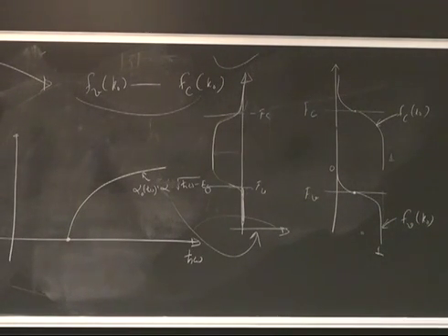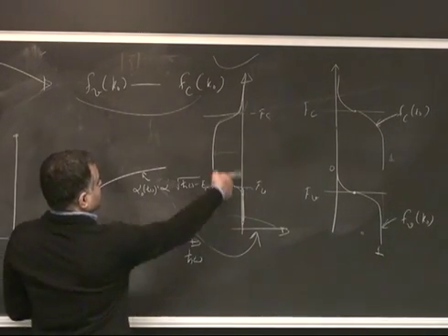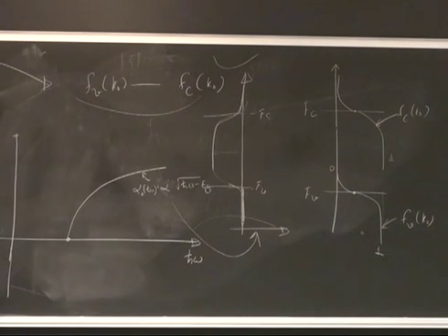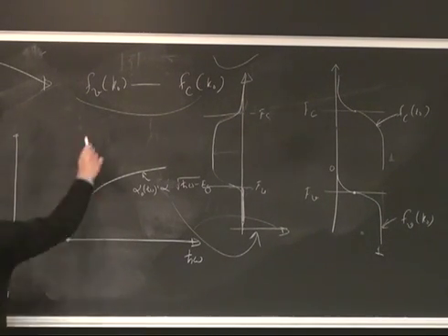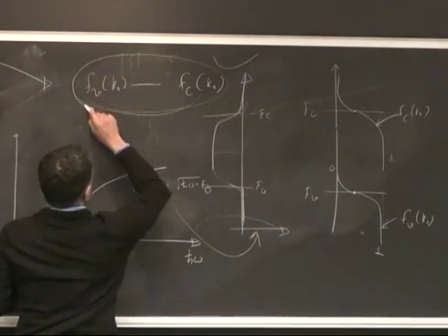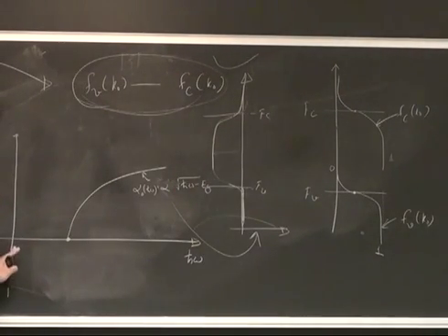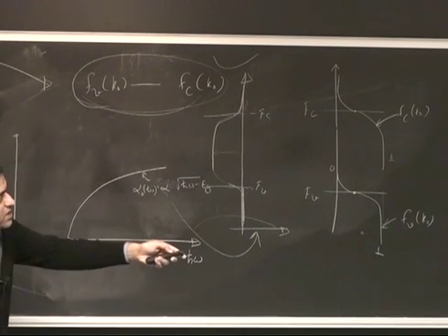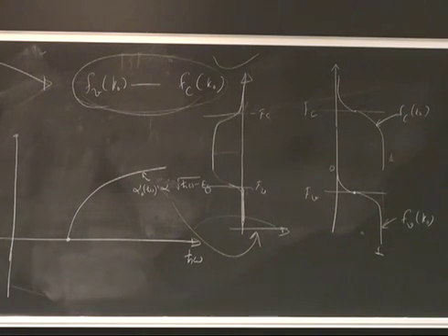Now what we're doing is multiplying with the difference function, and now I'm going to plot it not on this energy scale. What is even more important in a laser or LED is the photon energy. It's not the band structure energy, but the photon energy, h bar omega. So let's plot it versus h bar omega. So what am I doing? I'm plotting this quantity as a function of h bar omega. Where does h bar omega come into that? Well, it's sitting right there in the k0. You can just plug it in and find the difference.